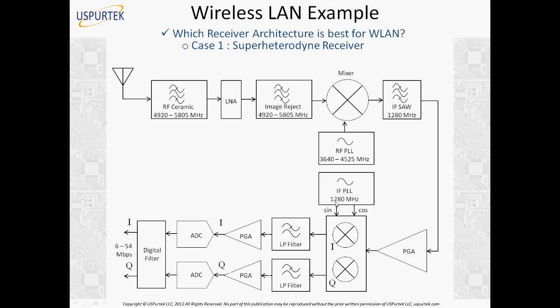So this is the same. All those benefits will be there. You have high gain and selectivity and all that stuff. It's a super heterodyne receiver, right? But what are the pros and cons of doing it like this? Pros, we have high gain with improved stability. There are no DC offsets. That means there is no DC component in the output signal because it's a super heterodyne receiver. We have better IQ matching at IF.